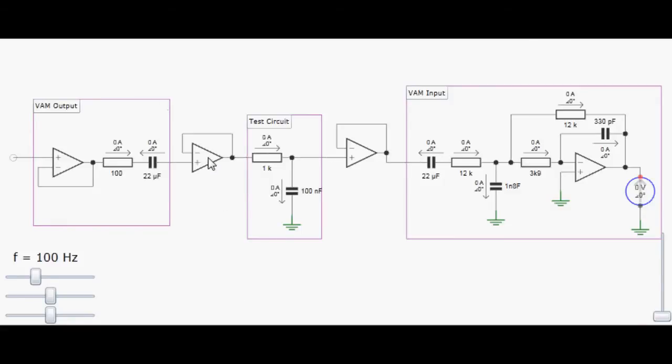Put a little op-amp follower there and an op-amp follower here. And choosing op-amps, the input impedance, looking into the non-inverting input, is so large it might as well be infinite. And the output impedance coming out of an op-amp voltage follower like this is so low, certainly much lower than 1K, that to all intents and purposes it behaves like it has a 0 ohm output impedance, and now we can determine the performance of our circuit.